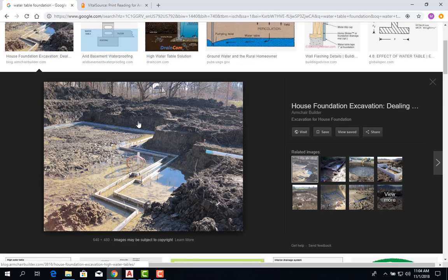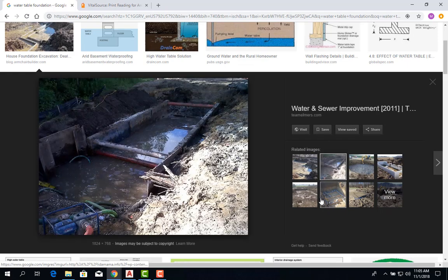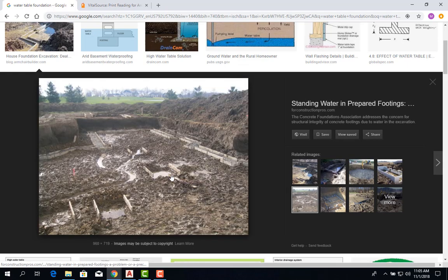If you would have done a geotechnical test, they'll catch this. Let's say they go like 5 feet underneath. There's a lot of moisture, there's a lot of water. When they pulled it up, there's a lot of mud in a certain section, so that's telling you there's water going through. That's one of the reasons you might want to do the geotechnical test, so you don't get these issues. The water table is too close to the surface, and that water is just seeping in, coming up.